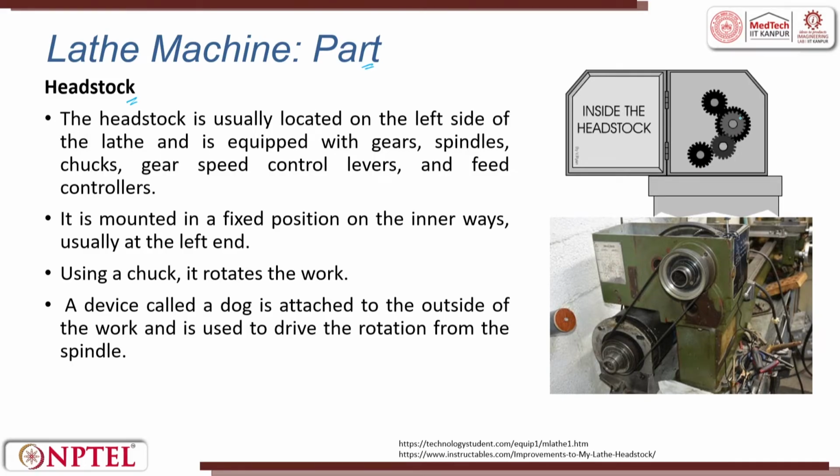So, the drive is given to this gear and then subsequently you try to transfer the motion from this gear to the meshing gears. If the gear size is smaller, you will have higher speeds. If it is larger, you will have lower speeds. And if it is larger, the torque will be very high. So, torque is basically used when you give a larger depth of cut, we use a high torque.